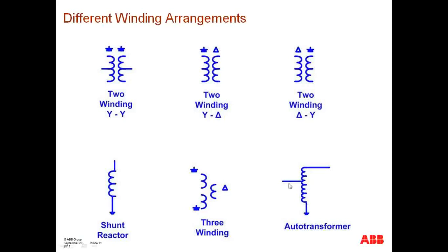And again, we could see in the case of the auto transformer, what makes the auto transformer different from a regular transformer is that the transfer of power from winding 1 to winding 2, or high voltage winding to low voltage winding, is not just because of magnetic coupling, but there's also some electrical coupling, because of the way this series winding is tapped.